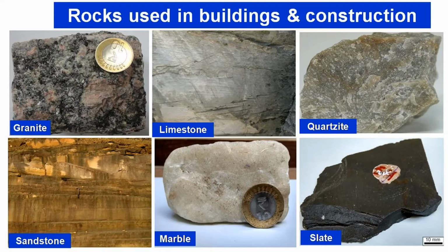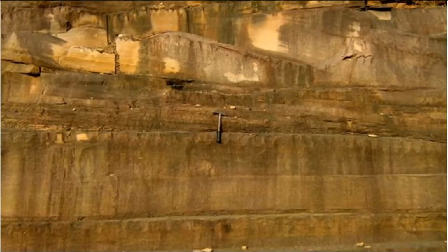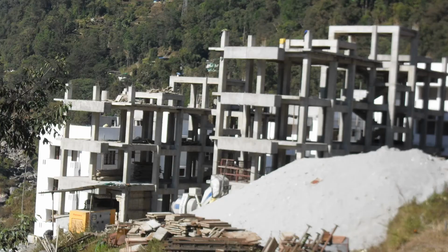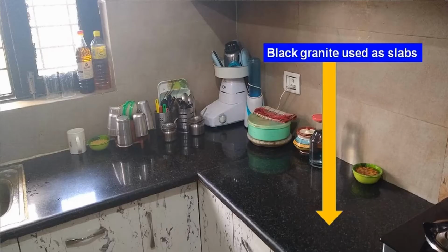Building stones like quartzite, sandstones, granites are used for construction of roads and buildings. Mostly, the locally occurring rocks are preferred because of neighborhood availability that reduces the transportation and cost considerations. Igneous rocks like granite are often used because of durability.